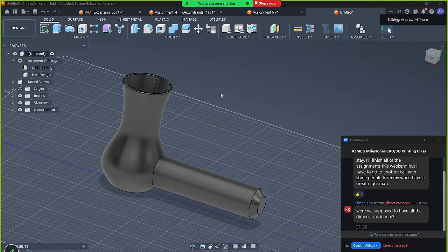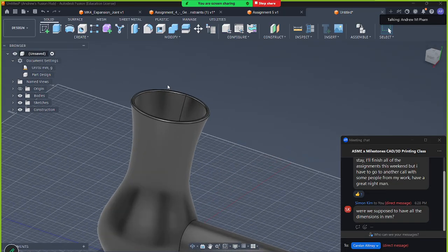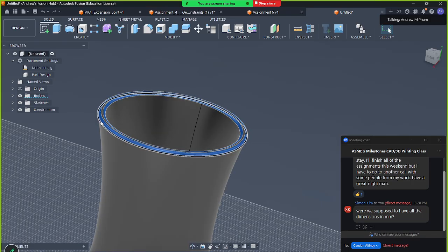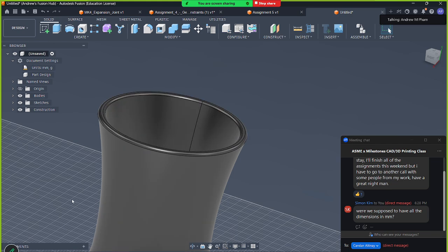So, you might remember earlier that I said that I'm going to purposely do something incorrectly. And what I did was I created a dependency in this case, right? So for this fillet here, I filleted both the outer and the inner edge, but this inner edge can only exist if the shell exists, right?